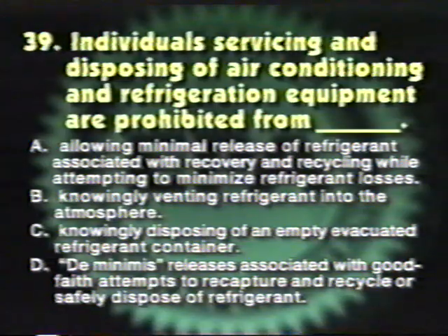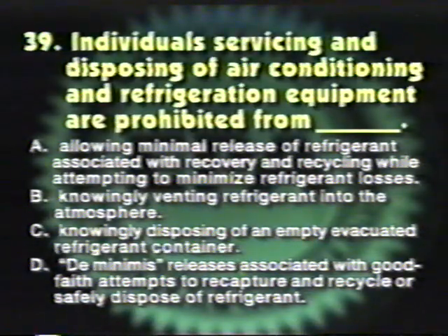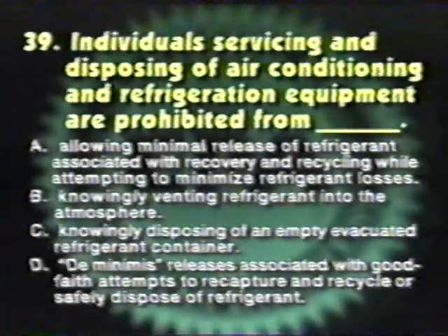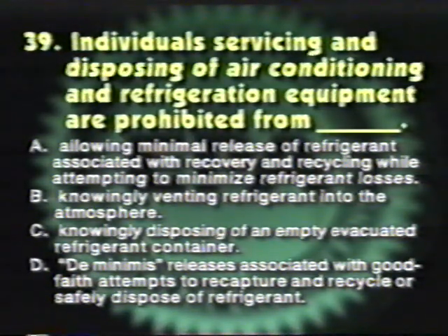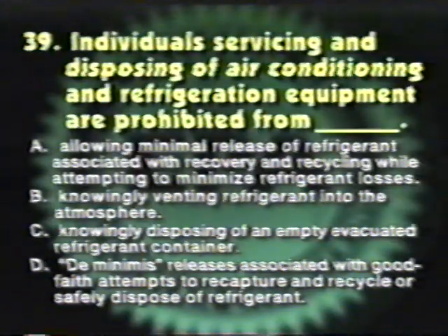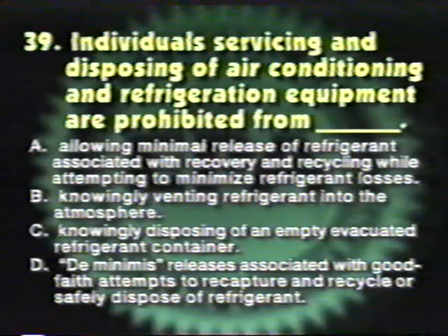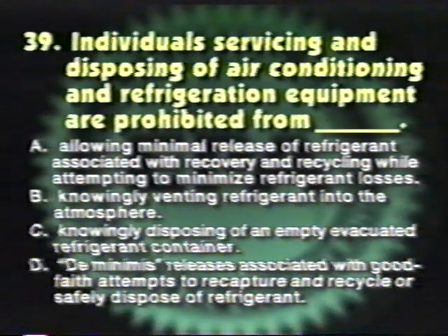Individuals servicing and disposing of air conditioning and refrigeration equipment are prohibited from A. Allowing minimal release of refrigerant associated with recovery and recycling while attempting to minimize refrigerant losses. B. Knowingly venting refrigerant into the atmosphere. C. Knowingly disposing of an empty evacuated refrigerant container. D. De minimis releases associated with good faith attempts to recapture and recycle or safely dispose of refrigerant.